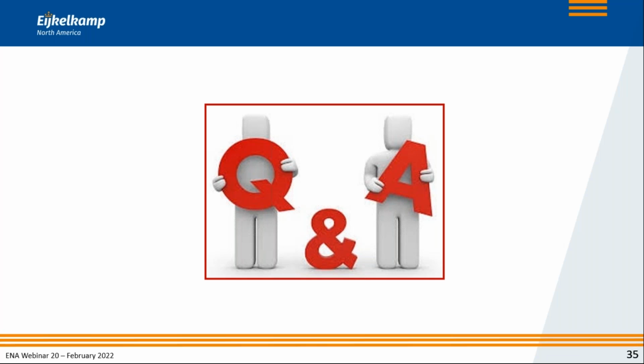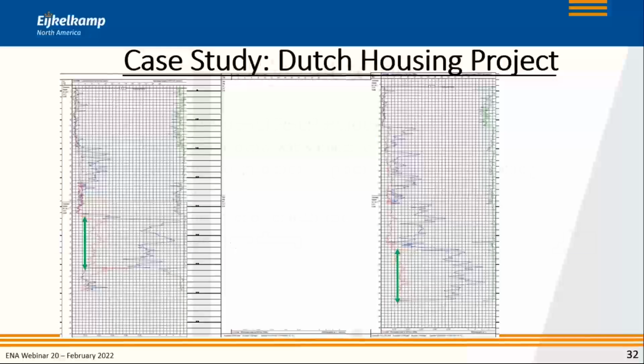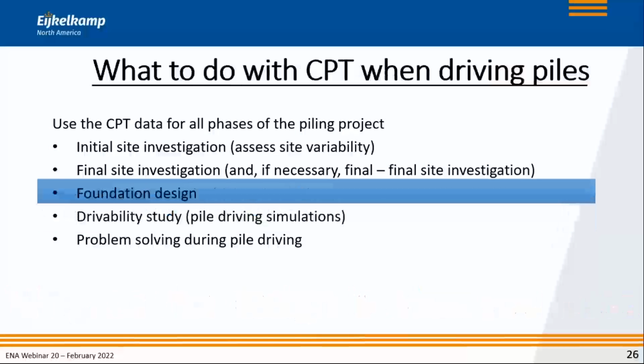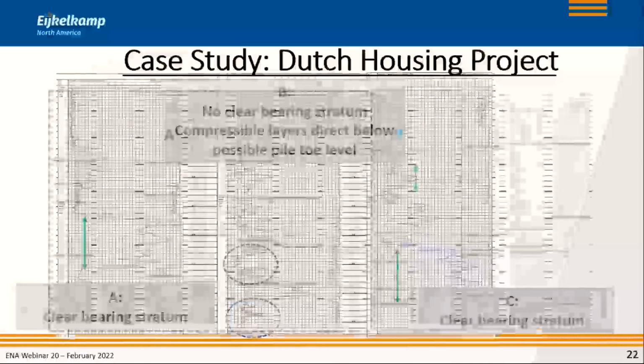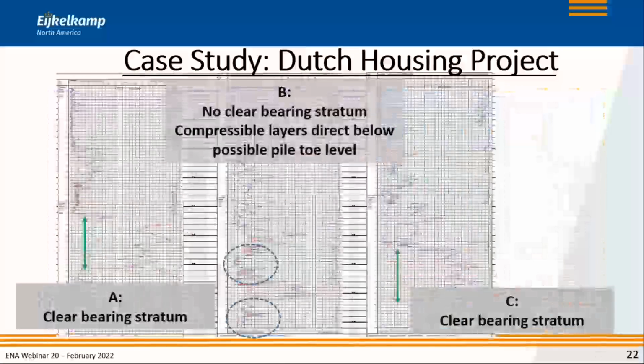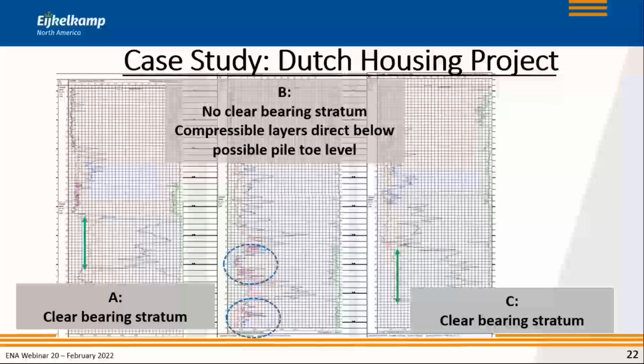Quite a few, actually. First of all, if you have precast piles, it basically means that you cannot really extend them all that easily. It's another reason why you need to do an extensive soil investigation to make sure that you have the variability correctly identified.